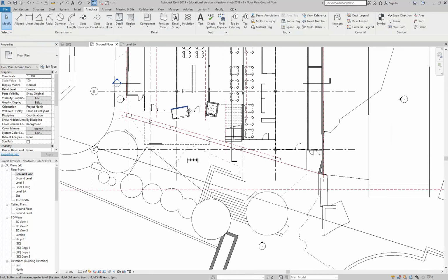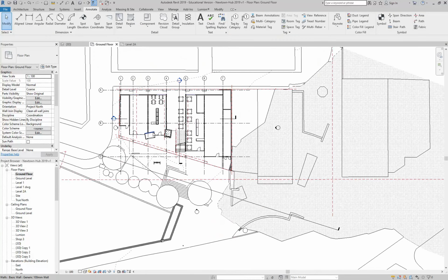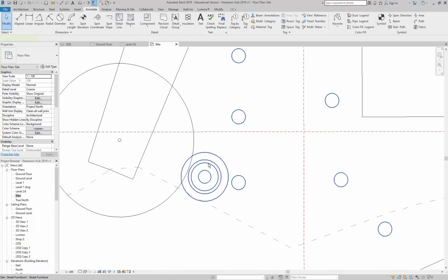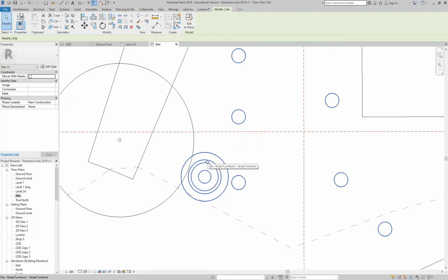Just let me know if there's anything else you can think of with Revit that you want me to go over. One thing would be to show us how to change a component that we just built, like an extrusion, into a family after you've already built it. Good example. I'll do that right now. I've got here how to change something that you've modelled using model in place into a separate family file.